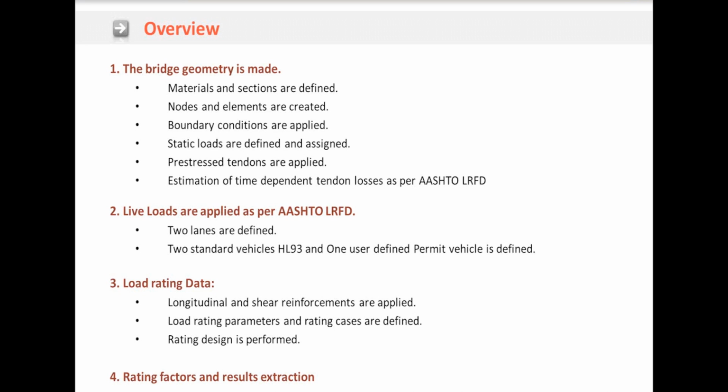But when it comes to, let's say, post-tension structures, or other types which are more complex than the conventional ones, then you need to model the bridge in certain software, get the result, and then use your spreadsheet, doing an iterative method: modeling a permit vehicle with a certain tonnage, taking the result to Excel, and performing the load rating there with the spreadsheet that you created in your company or got from the DOT.